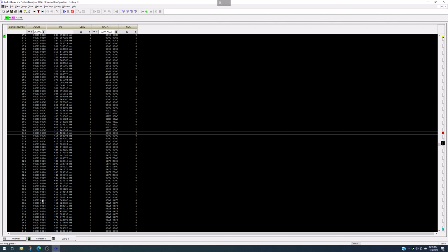So if I looked up earlier, 5AC was at 1ECB, and then I get down here further and we get 1ECC. So then the next one I would expect to see is 1ECD. The next time it does a write to it, at least it'll probably do a read from it first. So there's the read that it would have been doing, and I'm guessing, but I'm probably right on that. But then here's the 1ECD. So it's writing a value, then later it reads it, increments it, writes it. But I can see that happening in this list.